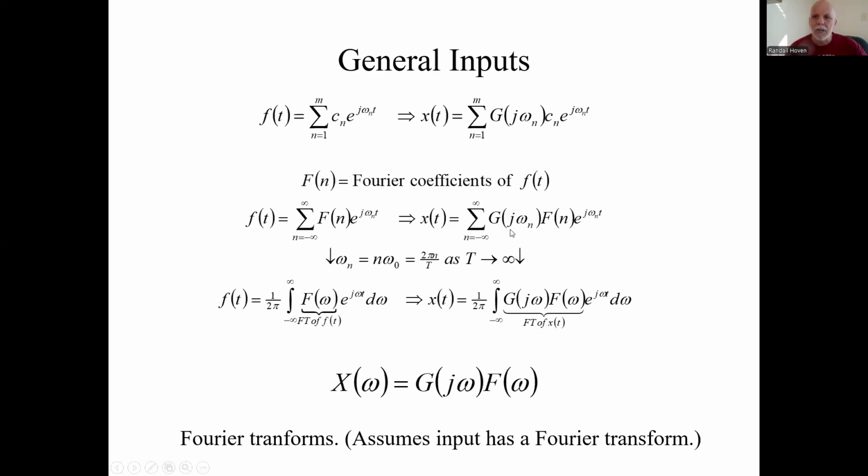So we can express an input signal first as a whole bunch of phasors, and you get the Fourier coefficients. You're basically taking the Fourier series. And then you could do it over an infinite number of frequencies. Fill up the entire real line of Fourier coefficients, and you get the Fourier transform.